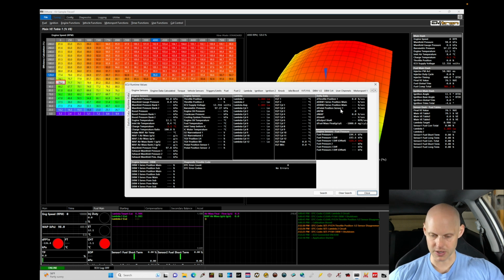Let's keep moving on here. Fuel pressure is showing here 194 kPa. The fuel pump has primed the system already a couple minutes ago before I started to film, so we're seeing that the fuel pressure is going to gradually start to taper down and dissipate because the check valve is slowly allowing that pressure to bleed off.